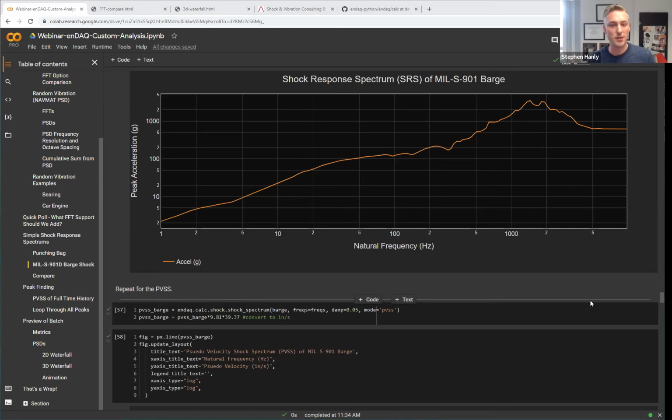Another point is that one of the benefits of the SRS is you're looking in the frequency domain. So if your noise is in a certain frequency range, it may become more obvious what's noise and what's real. Definitely play with that and see the result. It's going to matter how much noise you have and what frequencies those are at.